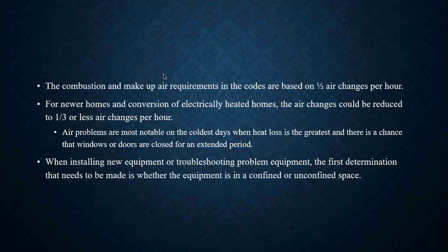It smells musty. Well, that's a sign that you don't have air changes going on in the home. So fresh air really should be brought into the home through some sort of mechanical means.